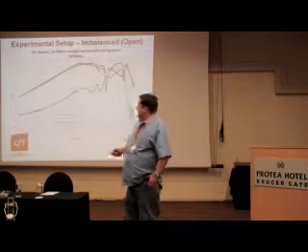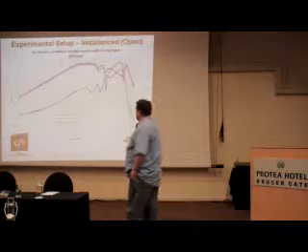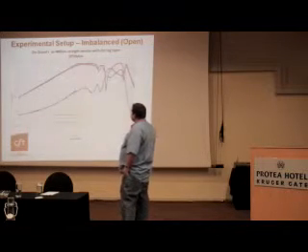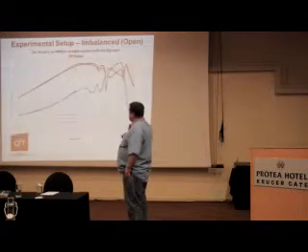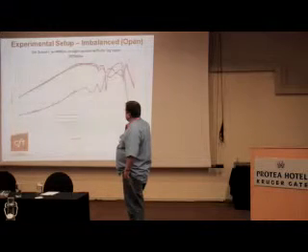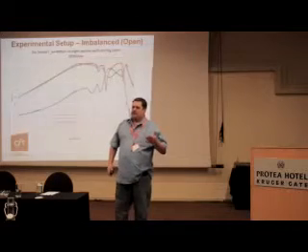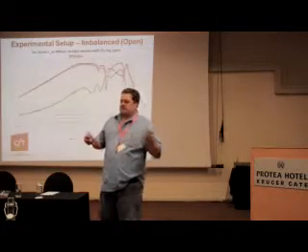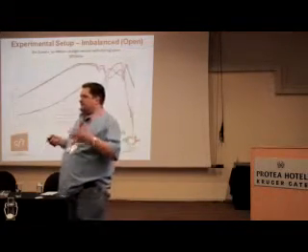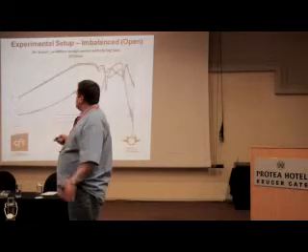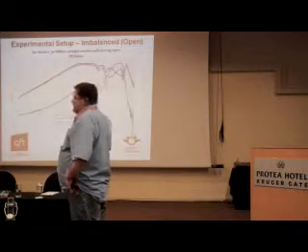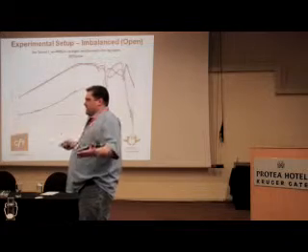This time, if you look at the lumped circuit behavior at the lower frequencies, you can see there's a lot of loss of signal, which is understandable because at low frequencies, close to DC, close to 50 hertz, close to a couple of kilohertz, the switch opens the circuit, and there should be a loss of signal.